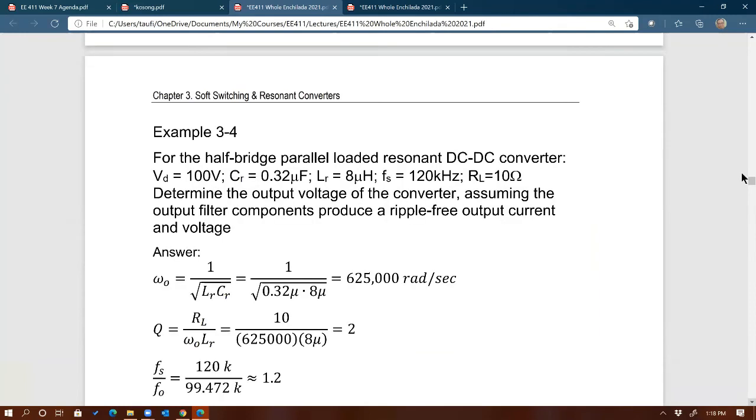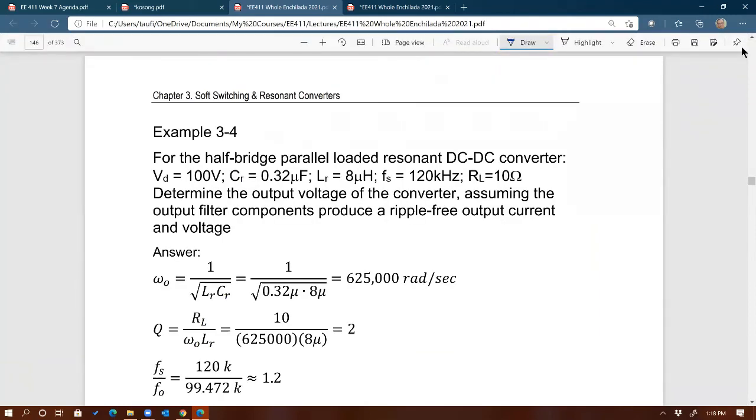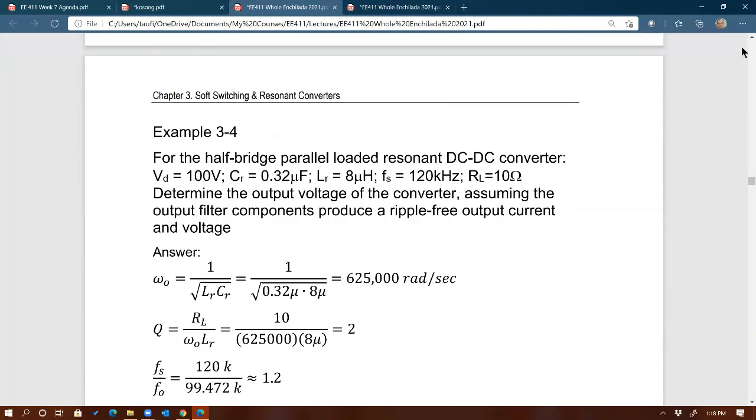Wait, could you use a switching filter, like a switching active filter? Yes, you could. You absolutely could. Expensive though, right? Because then you have to do all kinds of sensing. When you say active harmonic filter, do you mean sensing the frequency content and then adding a 180 degree phase shift to that content to cancel it? It's like a switched capacitor filter, because it's got to handle the power going through it. You can't just put an op amp in it, like a regular filter, because you can't drive however many watts through it.